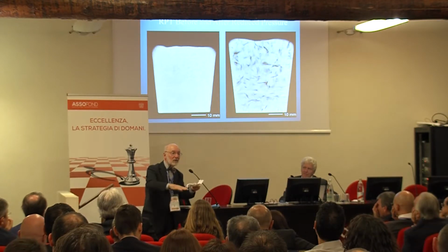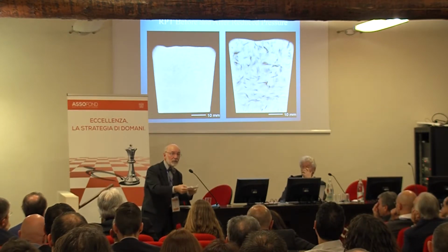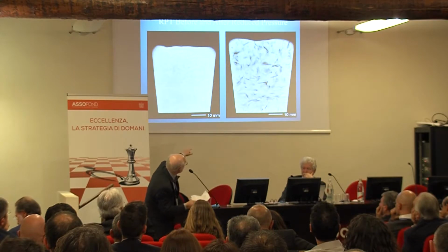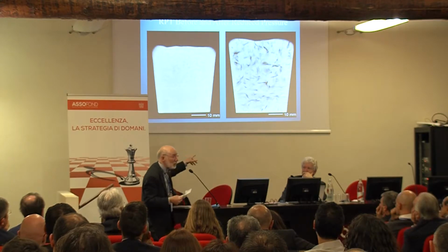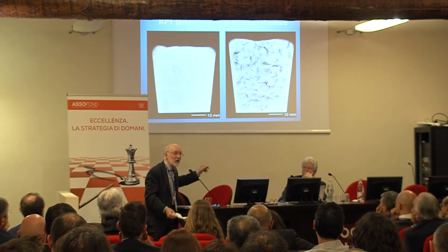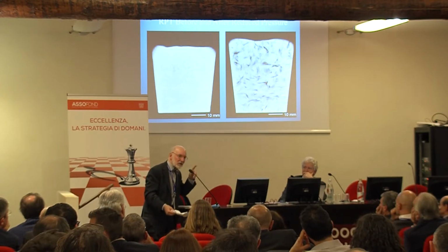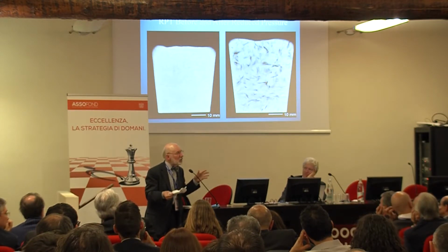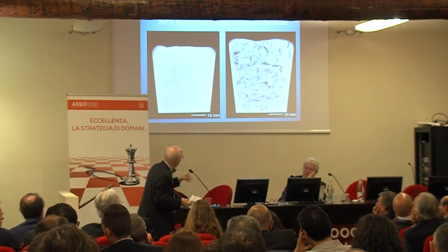And so if the pressure comes down because of, say, shrinkage in the casting, then this can open bifilms, and this rather funny shape I have, you can see the same funny shapes on the right-hand side. But just look how many cracks we have. It's full of cracks. And that's where our liquid metals now are, and why we're getting poor properties. Not so much poor, maybe, but mediocre. So, move on again.